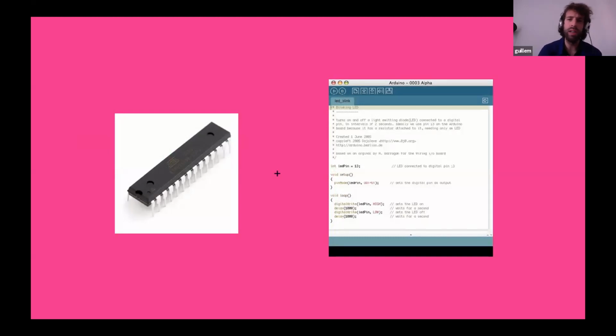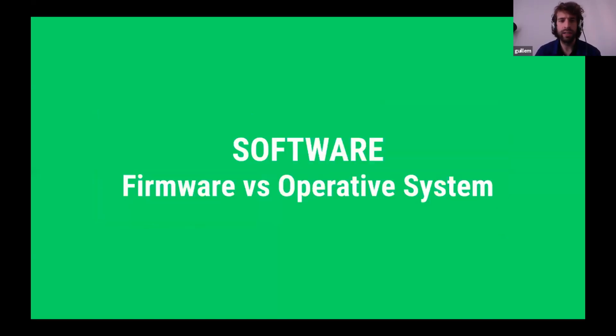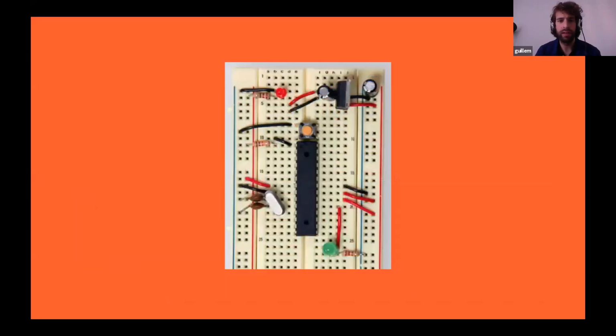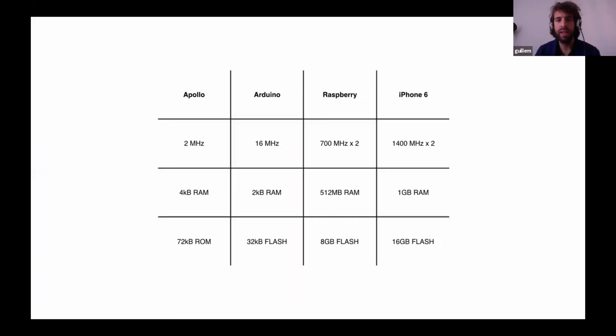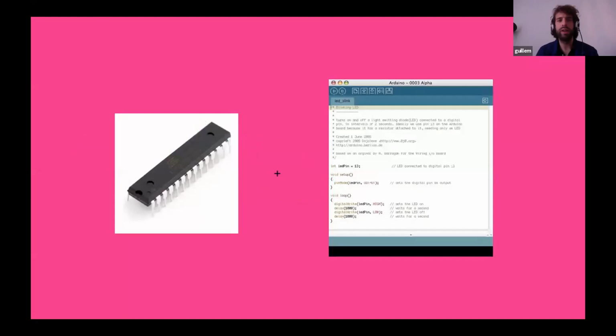So when we talk about programming a chip or dealing with a microcontroller, we talk about the hardware, but also about the software. And in fact, when people say the word Arduino, many times they think that an Arduino is this board here, or to make it clearer, people think it's this. This is an Arduino Uno, but for us in the Fab Lab, when we use the word Arduino, we usually refer to that: a specific chip that's compatible with the Arduino platform. And so we could use the Arduino software or another platform that uses the Arduino libraries, like PlatformIO, to code for that chip. This works because someone took the time to create neat libraries that implement the Arduino functions, like pinMode and digitalWrite, into the actual instructions the chip needs to operate.